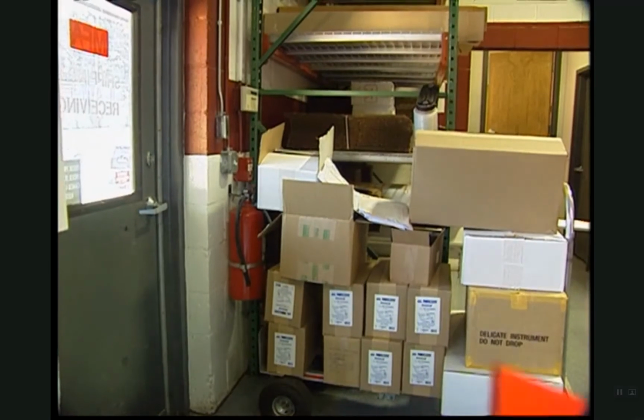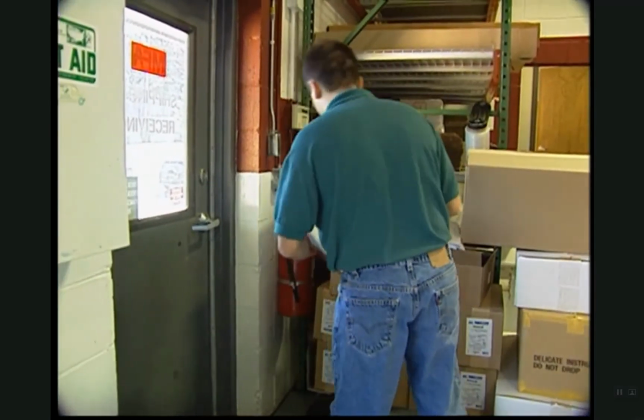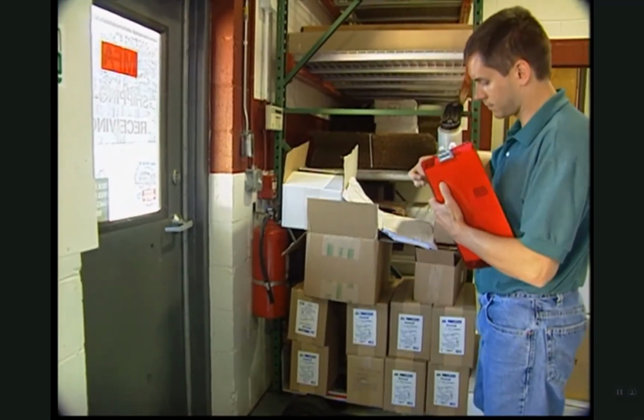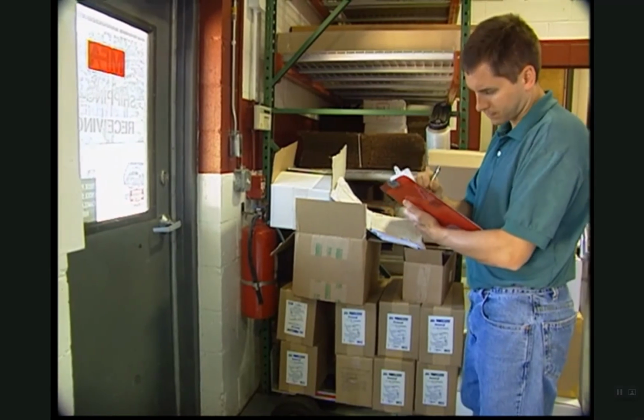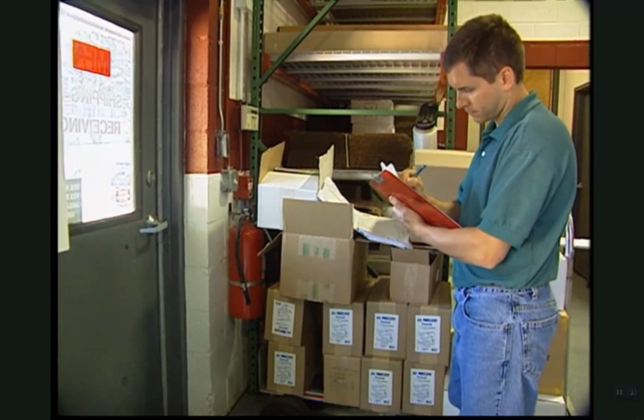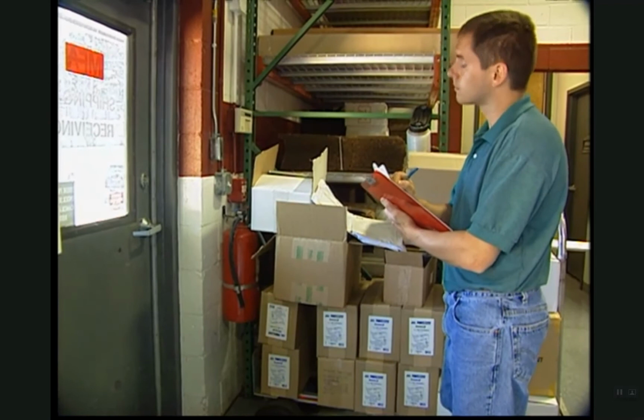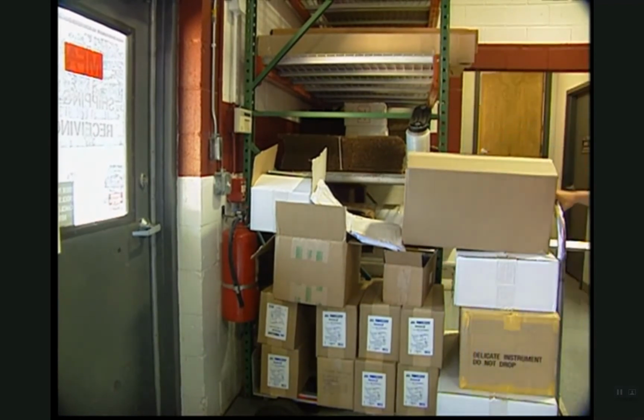Regular inspection and testing of fire alarm system components is essential to maintain system readiness. Inspection alone can spot many problems. For example, an occupant may place cartons or file cabinets in front of a manual fire alarm box, making it unusable. Conducting a visual inspection allows you to spot and eliminate this problem.